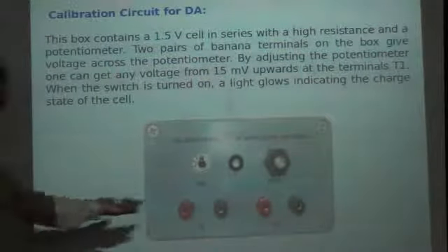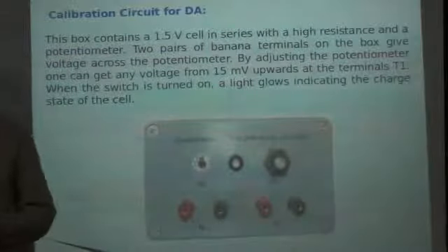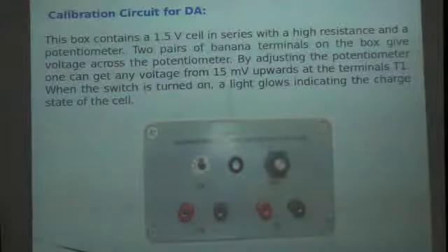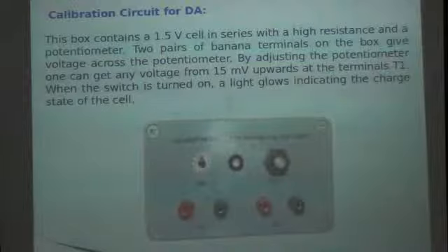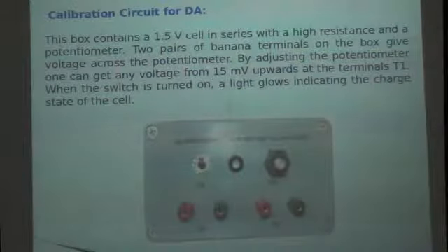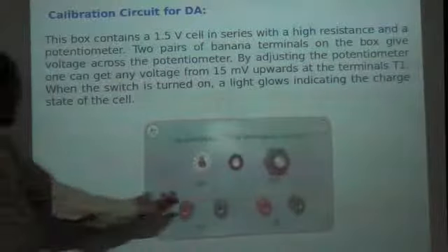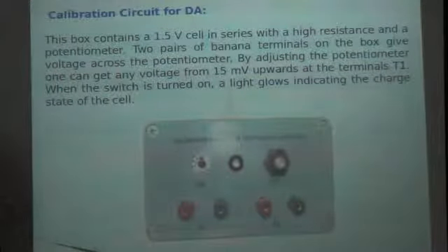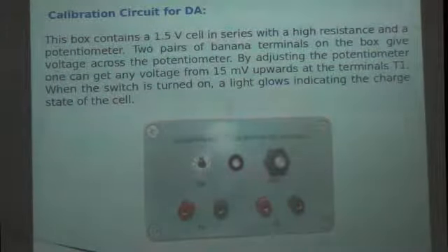Now you take out two leads connected to our DC differential amplifier, to I1 or I2 or I3. Let us say it's I1. So now you measure the output by using another digital multimeter at the output terminals of the DC differential amplifier. This 10 volt must be equal to 1000 volt because it is amplified 100 times. So you can do this also.